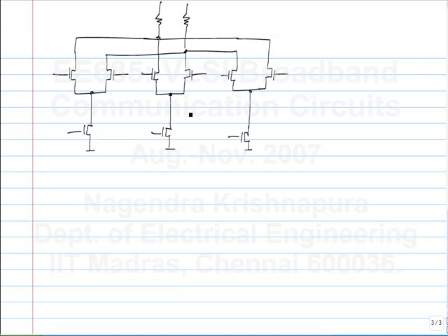So let's say I keep this fixed and this current comes from some current mirror, and just for simplicity I will keep the cursor value to be fixed. Sometimes it can also vary because you may not want to reduce the total amount of signal that you are transmitting, total amplitude of the signal that you are transmitting, then you reduce or increase everything. But let's say the cursor current is fixed and I want these two to be variable.